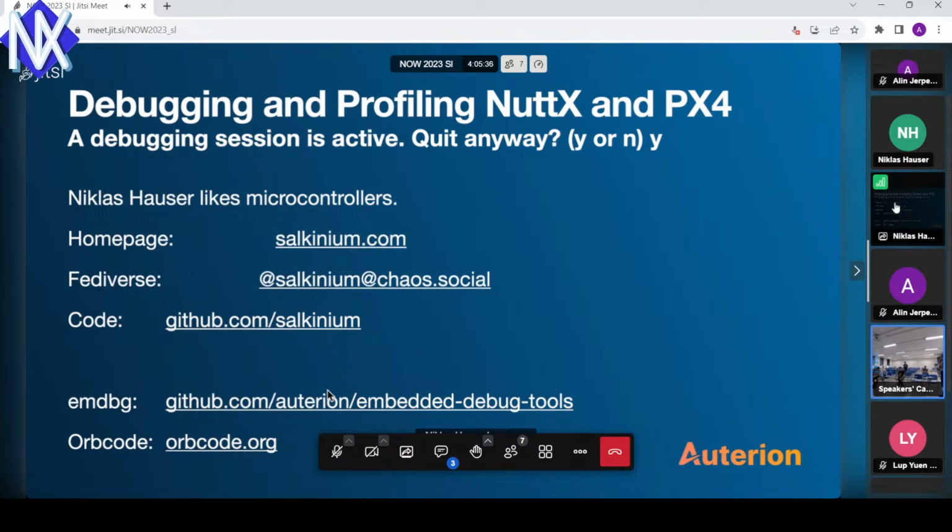Because here we are talking from a university, a school, and well, the simplest debugging interfaces are printfs and GPIO toggling, or even JTAG and J-Link is common, but it's not available for all kinds of OSs, and it's even worse when we are talking about bare metal programming. So could you highlight the most interesting, the most useful tools you have been using with NuttX, please? From your perspective, of course, that's very personal.